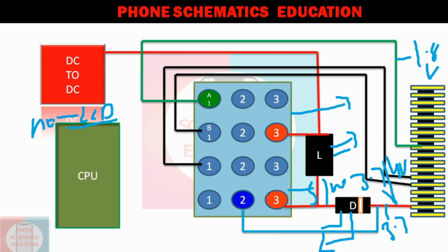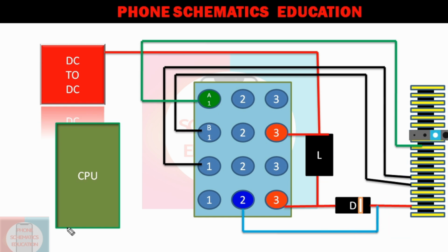The mind does not work. So where is the fault? I will tell you. Sometimes when water contacts this IC, or any shorting, the connection between this D3 pin and this coil is lost. There is no connectivity.